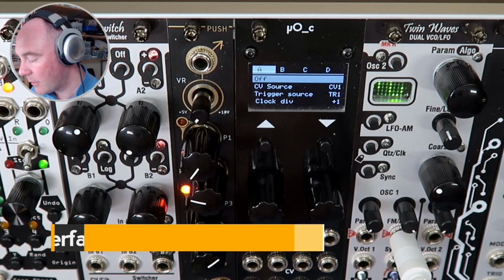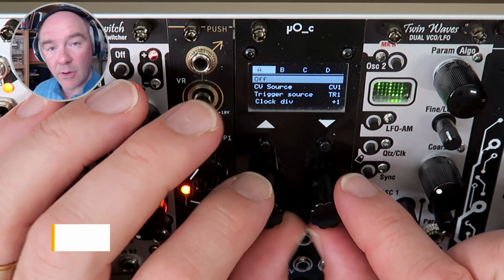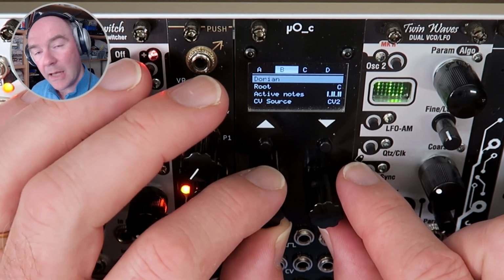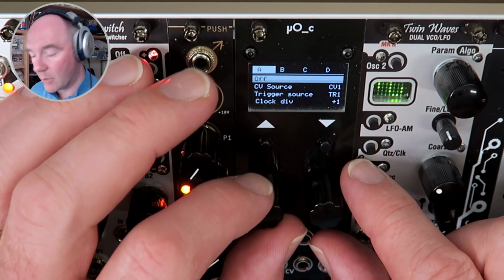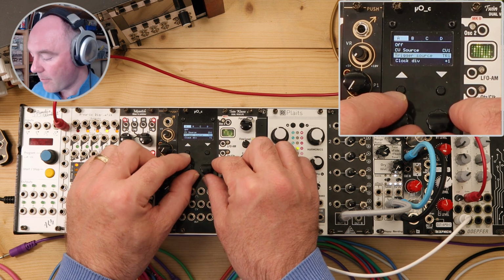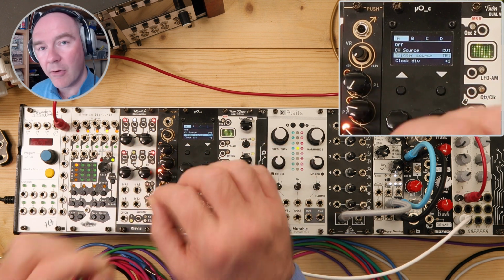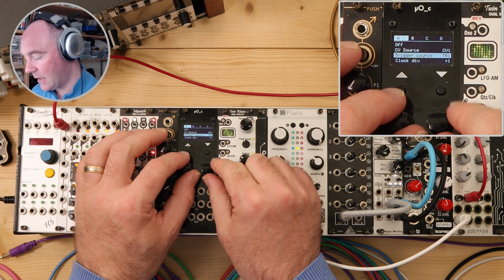Now let's do a quick review of the user interface. There are 4 quantisers in Quantermain, A, B, C, and D, and you access them using the left knob. You just turn it and you can select the quantiser. As you're selecting the quantiser, the selection bar remains on the same parameter each time, so you can compare quantisers and change the same setting very easily.